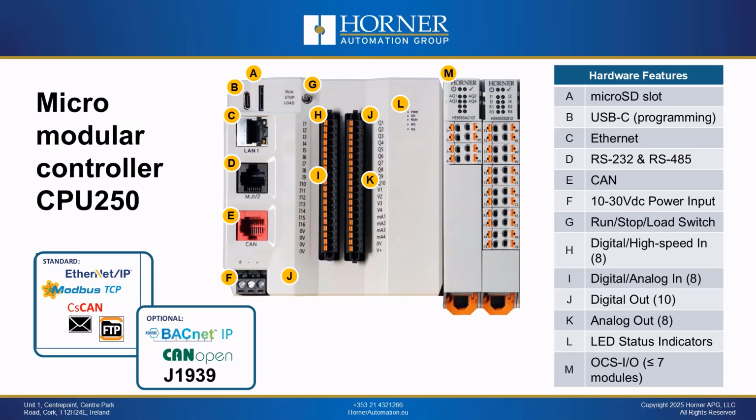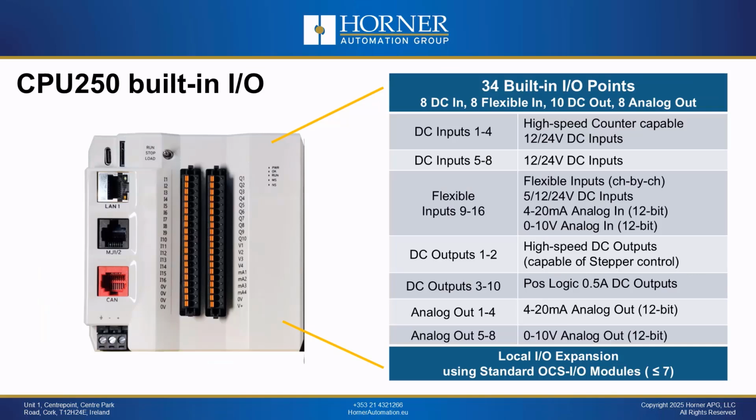You can also add additional I/O through standard OCS I/O blocks that you can add on the side of the unit, and all kinds of different protocols are supported. There are 34 built-in I/O points in total, including 8 of which are flexible between digital and analog.